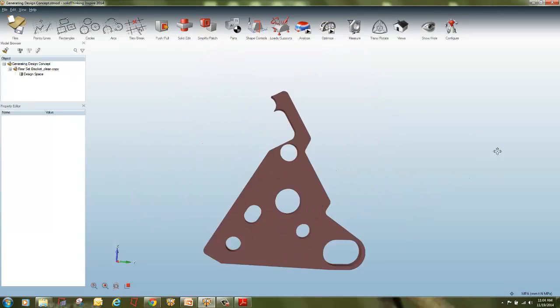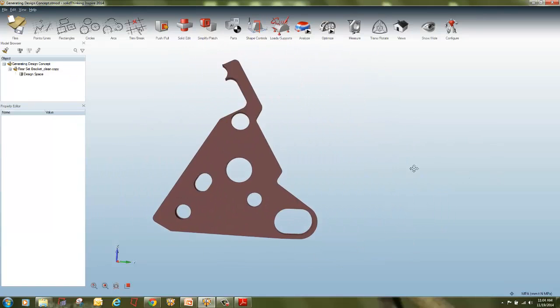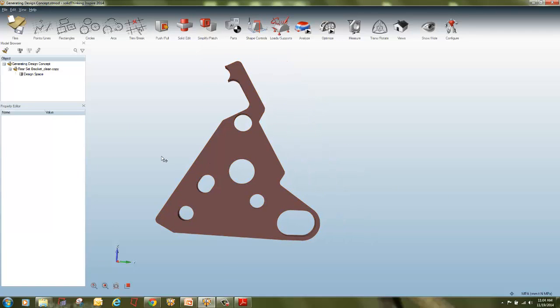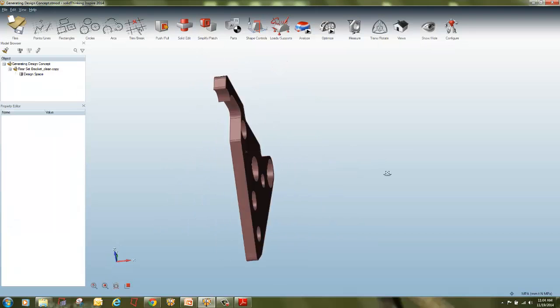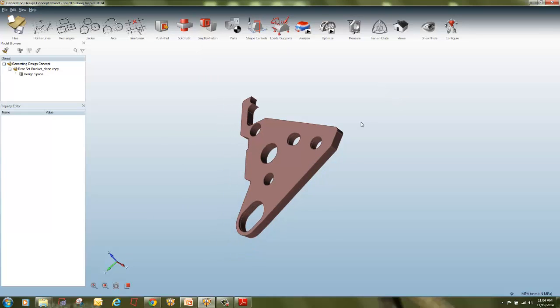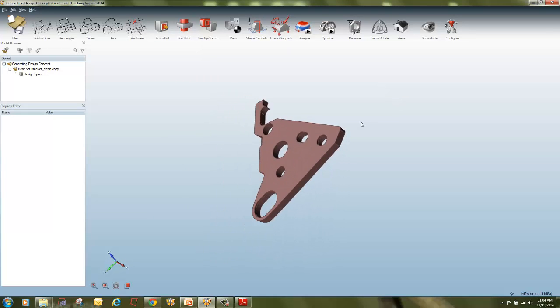That is, in HyperWorks, Shift plus right mouse button pans the model and Control plus right mouse button rotates the model. Scroll up and scroll down to zoom in and zoom out. Then turntable versus trackball rotation. Inspire offers two types of camera rotation. Use the right mouse button for turntable rotation, which is useful when your model's vertical direction is aligned with the z-axis. Hold down the middle mouse button for trackball rotation, which is useful for tumbling your model in any direction.